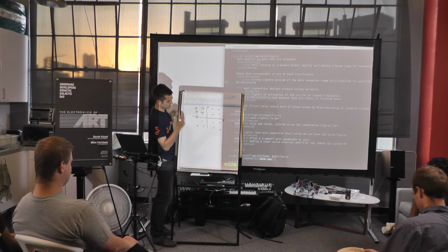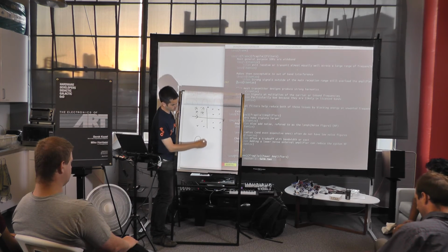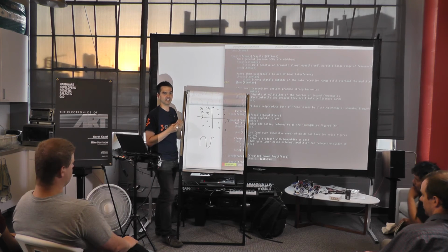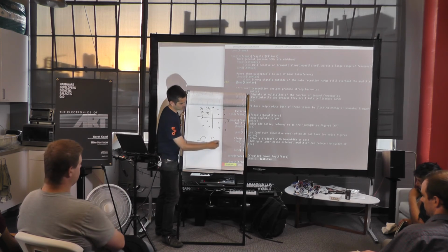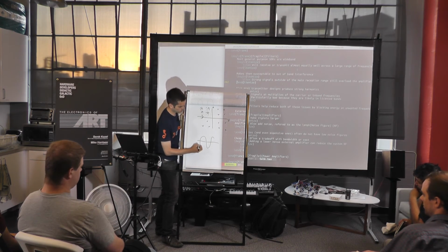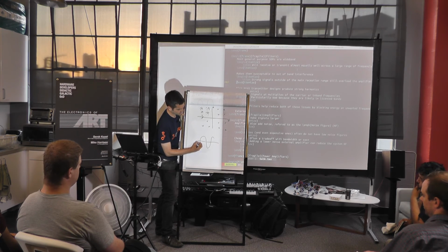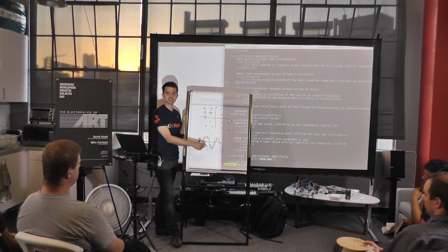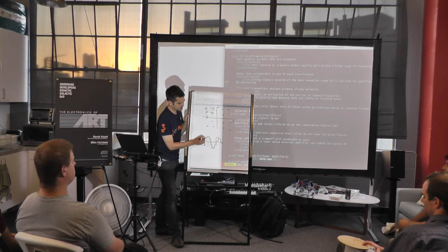There we go. So again, if you have a waveform that's like that, but say we had a really, really cheap analog to digital converter that only had 4 different levels, and you managed to center it around the center, what you would end up with is, it's 0, and somewhere around here it jumps up, and it's gone to another level, drops down. You would end up with something that's still, I'm drawing this rather badly, but you get the idea. It's a quantized sine wave. And so there's an error here.